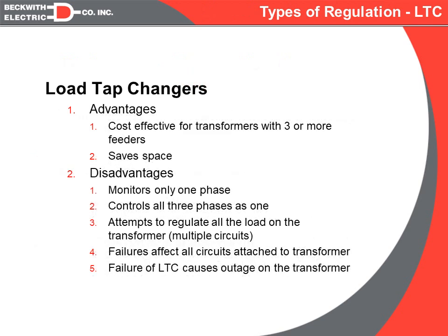So, keeping all this in mind, we will start with the load tap changing transformer. The reason you would have a load tap changing transformer in the substation is typically because of space. Load tap changing transformers take up less footprint than either bus or feeder regulation we're going to be talking about next. So if we are in a metropolitan area where land is very expensive and we want to get as many transformers and feeders into the footprint as possible, we would want to use load tap changing transformers.